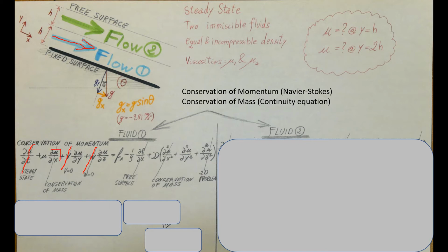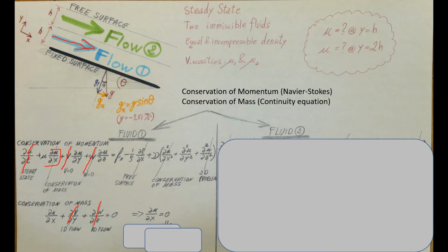Let's take a look at this term right here. For this one, we're gonna go to the conservation of mass. Here it is, the incompressible form, and we can see the three terms. This one and this one we can cross out, as we discussed, because we're dealing with a one-dimensional flow, and all we have left is the change of u with respect to x. That's exactly what we wanted because it's gonna allow us to cross out this term. Mathematically speaking, if the derivative of something is 0, then if we take another derivative of it, that'll also be 0. Therefore, this term also goes to 0.